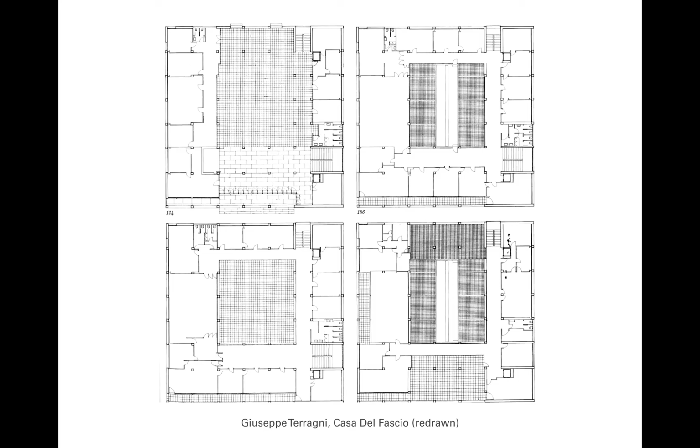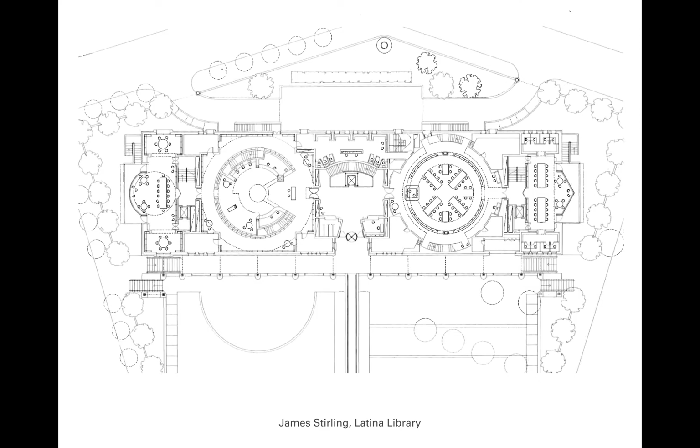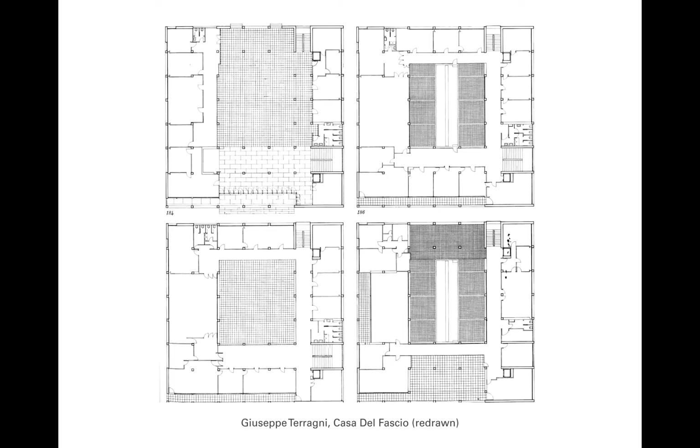This, I also recommend, in both of these cases, there's no poché in the plan. In other words, the sectional material that's being cut in the plan, the columns, the walls, are left white with a heavier black line around them, and it makes it much more legible.